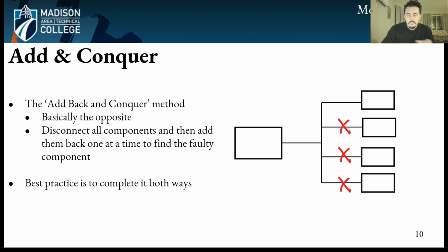And the inverse of this would just be to add components. So basically disconnect everything and add components back. So it's best practice to complete this in both ways, so we can really figure out which of these components is causing the issue and be dead sure before we move on to proposing a solution.